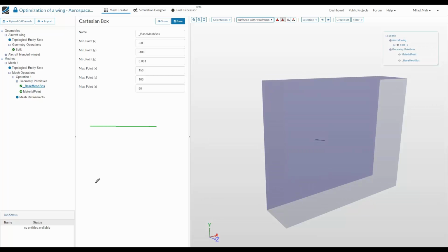Just imagine this is your flow channel, and this is your wing. It's a very extreme example. Then your streamlines would look like this and be influenced by your box. And that's the reason why we use a larger size. By the way, because Erimantis asked, all settings on SimScale have to be defined in standard units. So this is meter, kilogram, newton, etc.